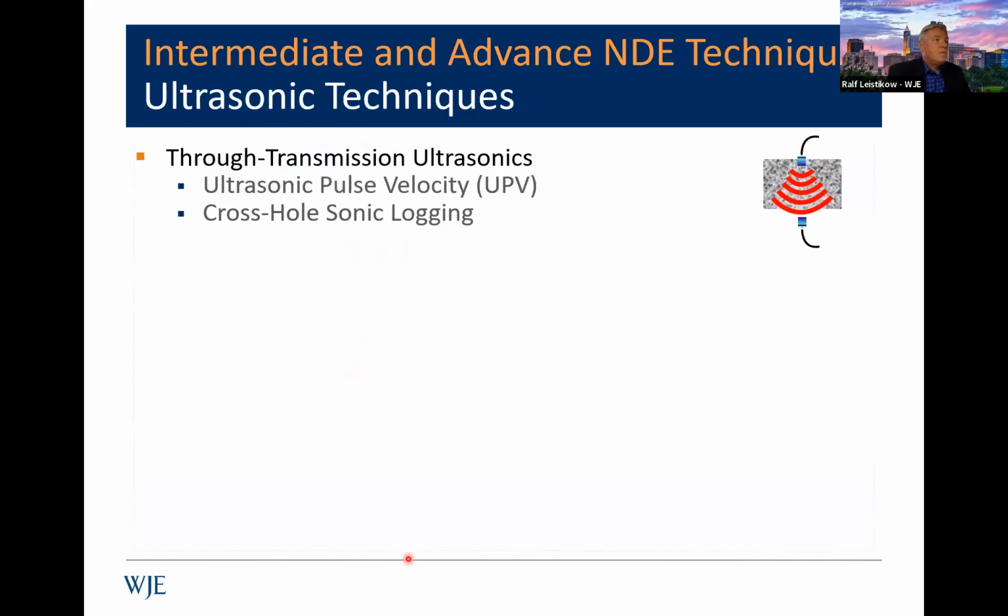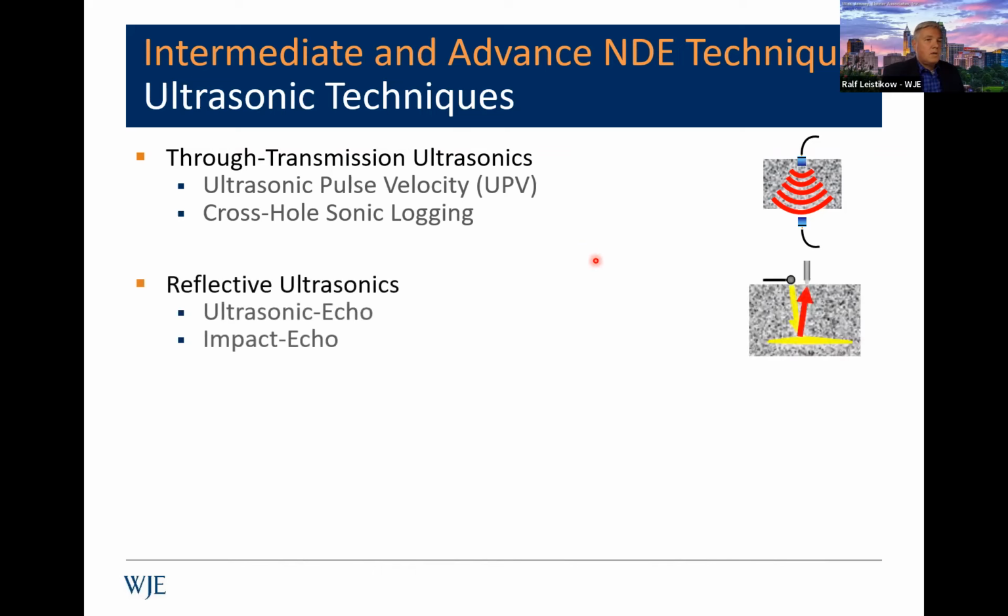So now I'm going to get into more advanced, potentially NDE techniques that are more ultrasonics related, and part of that is through transmission ultrasonics, ultrasonic pulse velocity, and cross-hole sonic logging. You can see schematically here, you basically have to have access to both sides of a slab, a column, or whatnot. That may be a disadvantage. I'm going to go into more detail about each of these.